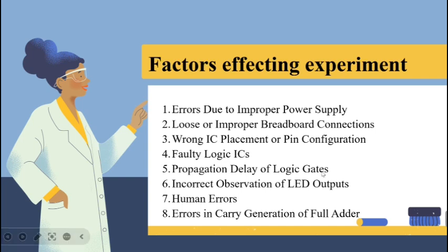The fifth one, propagation delay of logic gates. Logic gates do not respond instantly. Every gate has a finite propagation delay between input change and output response. This becomes important in a full adder because multiple gates are connected in series.